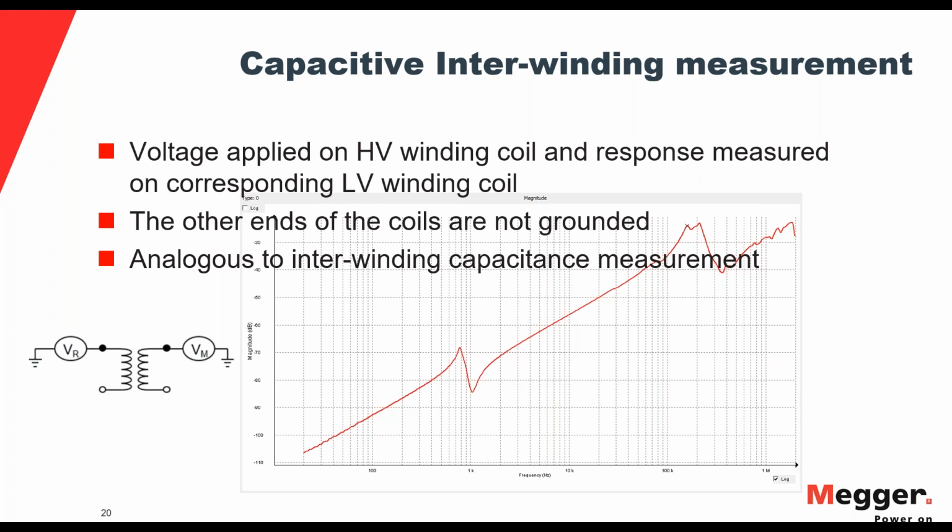One of the other tests that's done on the transformer is a power factor test. In a power factor test, you test the capacitances between windings and between the winding and the ground. And you get power factor values which are indicative of the quality of the insulation, but you also get capacitance values which tell you about the geometry of the windings. So you do look into the physical aspect when you do a power factor test as well.